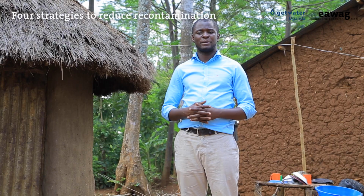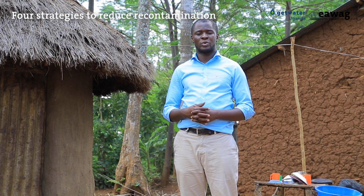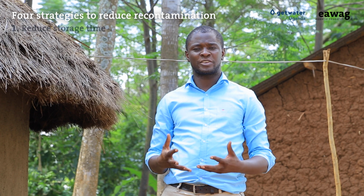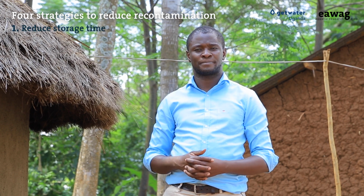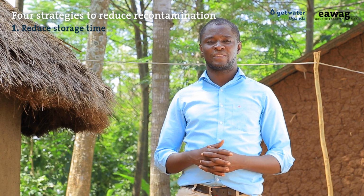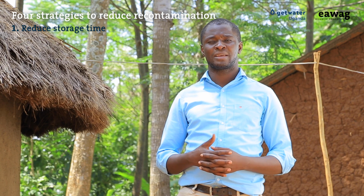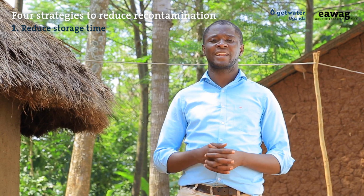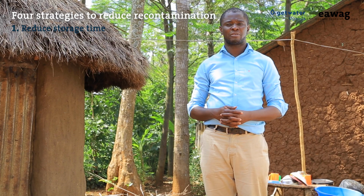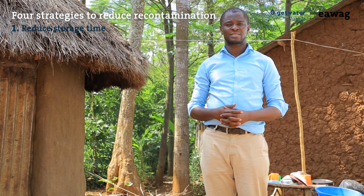Four strategies can be implemented to reduce the risk of contaminating treated water. The first strategy is straightforward: reduce the water storage period. At the clean water tank, this can be achieved through high turnover, meaning balancing the amount of water that is produced and that is consumed. At the household level, clean water should be consumed within 24 hours.